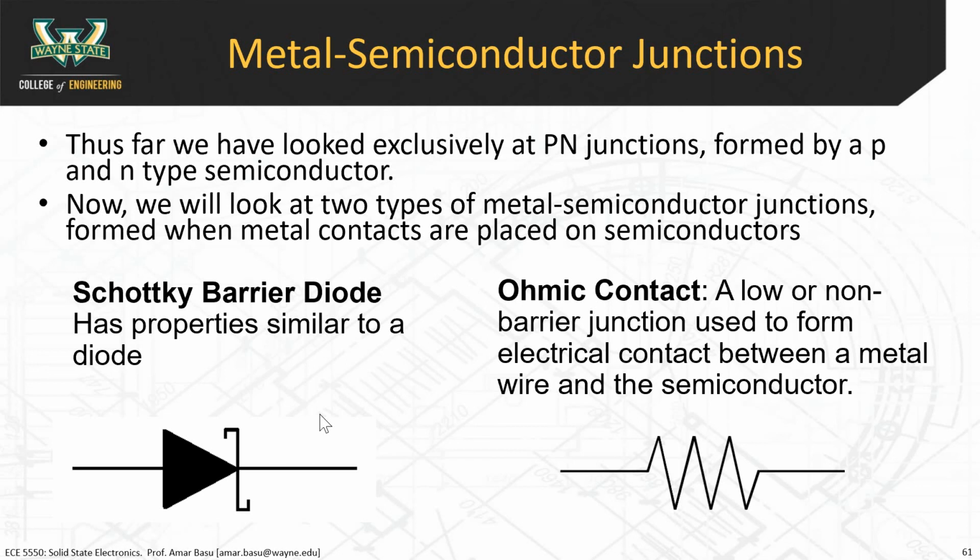Well, diodes are used in some types of circuits, but if you look at the majority of integrated circuits today, almost all of it is digital microprocessors. The digital microprocessors are all MOSFETs, NMOS, PMOS devices. The diodes, I would say, are used for electrostatic discharge protection. And because a MOSFET has N and P regions, it's going to have some diode-like properties that you have to be careful about if you don't design it properly. In terms of integrated circuits, a lot of light sensors use diodes.